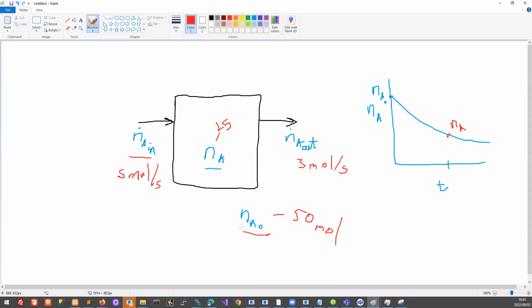And very quickly, we'll come to differential equations and differential balances. And if you don't have a grasp on this basic thing, it will seem totally confusing. So just remember, the flow rates are very different to the holdups. And in the holdups, you have the time variable. There's a difference between the initial amount and the current amount. And that's different to the inlet flow rate and the outlet flow rate.